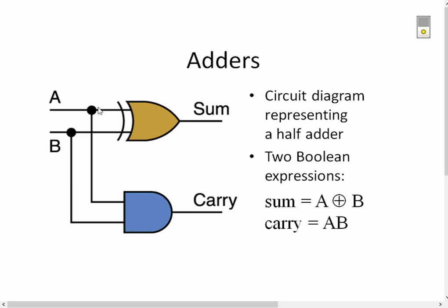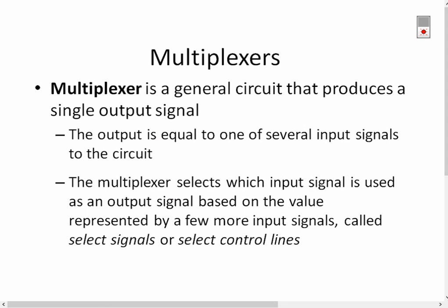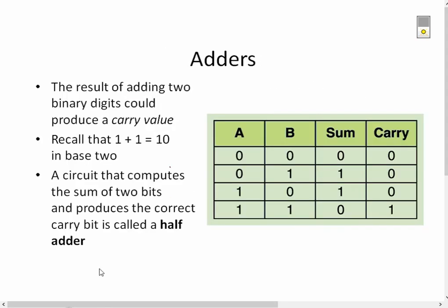And we also know that the exclusive OR says that I'm going to have an output of 1 if A is 1 or B is 1, but not if both of them are 1, and not if neither one is 1. So when I put this functionality together and I create a truth table on this, what we're going to find is that I've actually implemented the truth table that's represented here in the adder circuit.